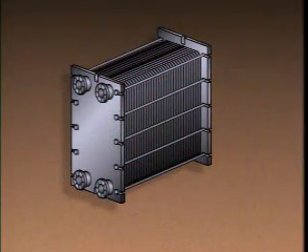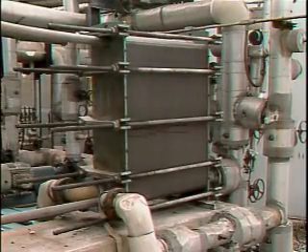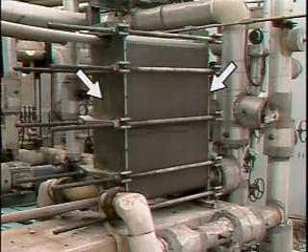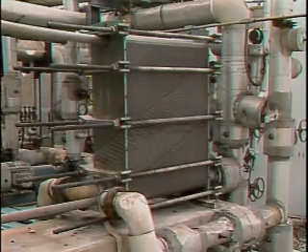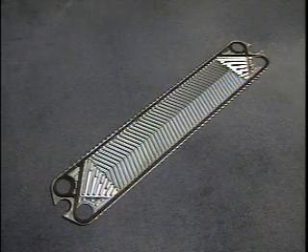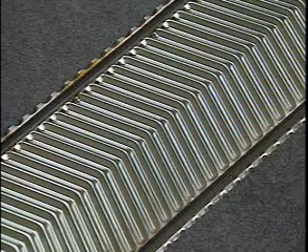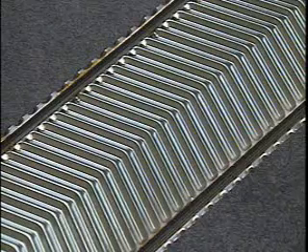Keep in mind that the plates are actually back to back, so the two fluids pass each other on opposite sides of a plate, moving in opposite directions. This plate heat exchanger consists of a series of thin metal plates and two fixed end plates. The end plates are used to help support the other plates, and they hold the fluid inlets and outlets. The plates inside the heat exchanger have a corrugated or ridged surface. The ridges cause turbulence as the fluid passes over the plate. The turbulence helps increase the amount of heat that's transferred.